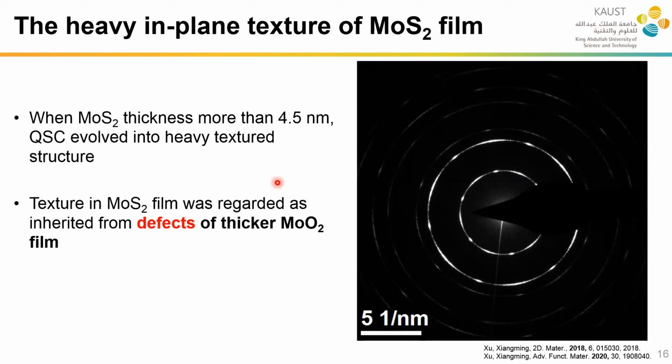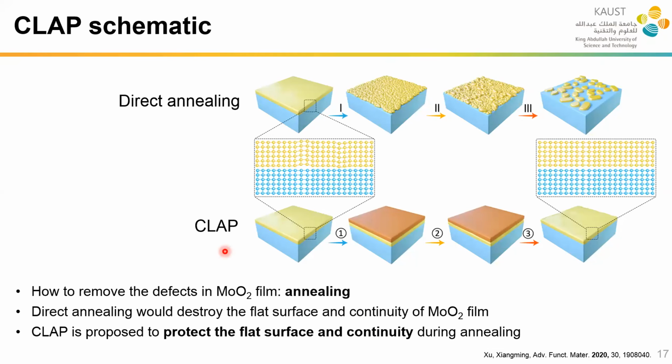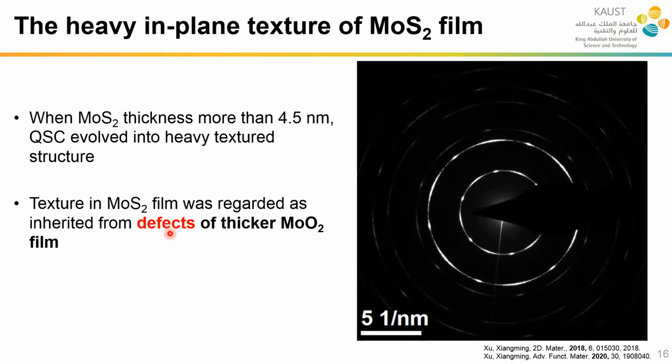So we were thinking that maybe the reason is that the thicker epitaxial precursor film has more defects such as dislocations. Actually, this is common in the area of epitaxial growth. If we increase the thickness, the dislocation defects will increase. It will be very obvious. So we thought that if we have defects, we just need to minimize them, but it's not that simple, because even though here we say it's thicker, it's also very thin. It's just 5 to 10 nanometers.